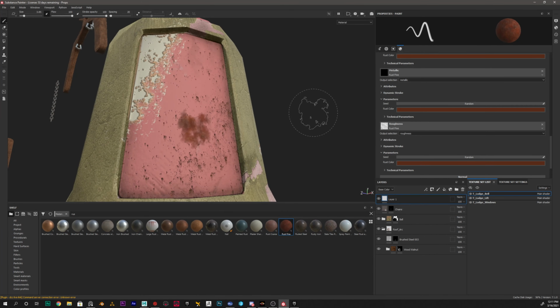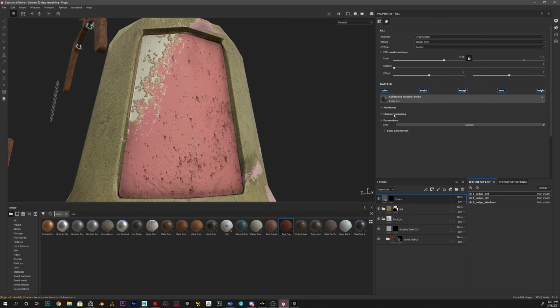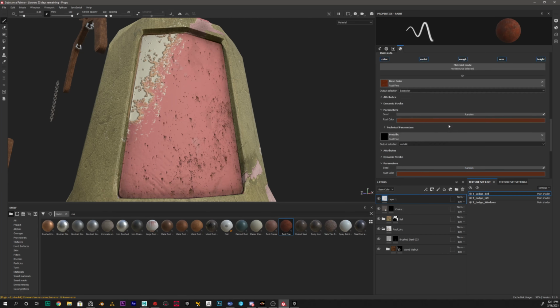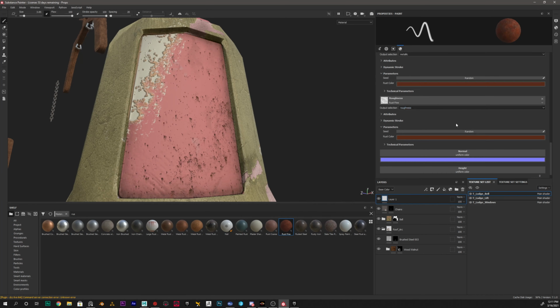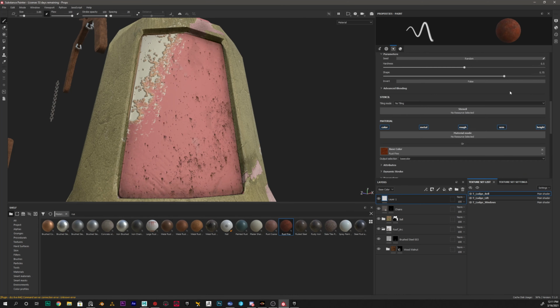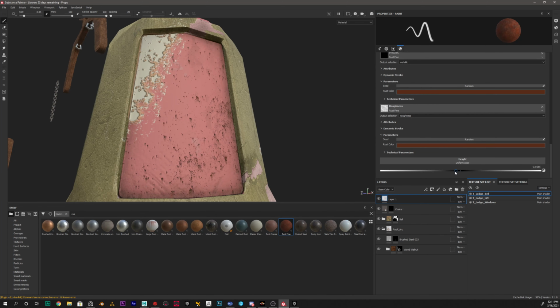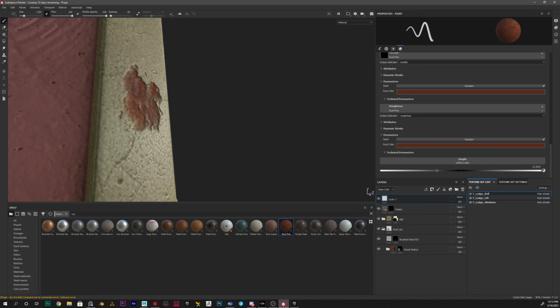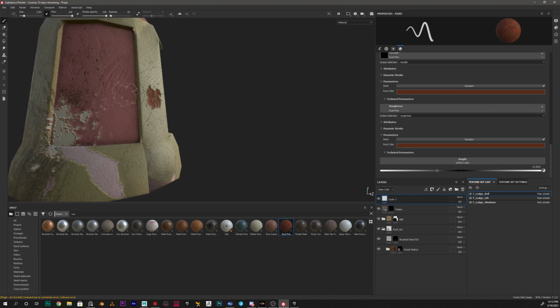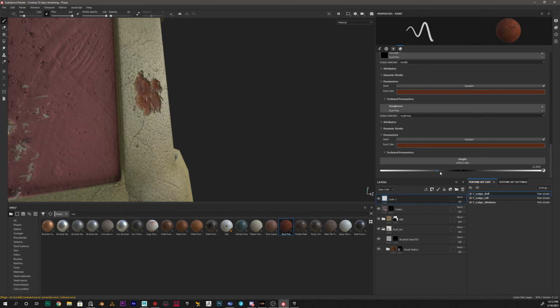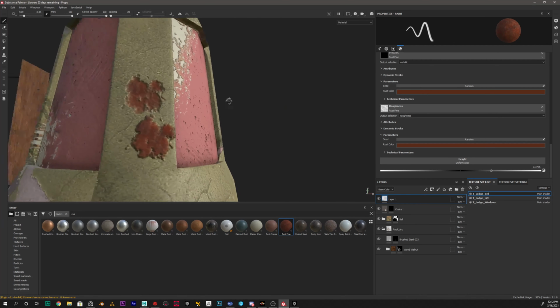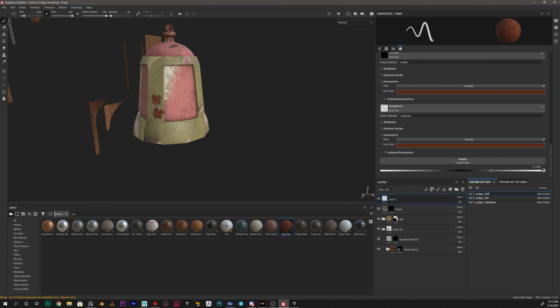See? And you get that information for those channels. Oh, by mistake, move to. So there you go, you got all three. And then what I did was I unchecked. I don't need a normal map for this, but I left the height. And what I did is just brought the height down. So every time I click on it, you can see the indent. And I could do that, or I can bring it forward so that the rust comes out. And that's all I did for these.